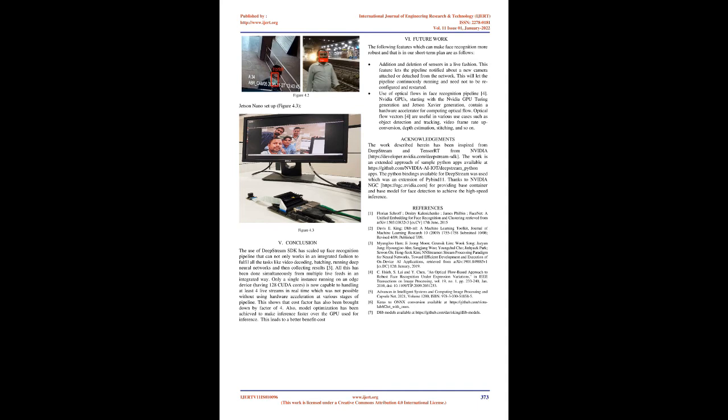Figure 4.3. V. Conclusion. The use of the DeepStream SDK has scaled up the face recognition pipeline, which can not only work in an integrated fashion to fulfill all the tasks like video decoding, batching, running deep neural networks and then collecting results, but all this has been done simultaneously from multiple live feeds in an integrated way. Only a single instance running on an edge device, having 128 CUDA cores, is now capable of handling at least 4 live streams in real time, which was not possible without using hardware acceleration at various stages of the pipeline. This shows that the cost factor has also been brought down by a factor of 4.